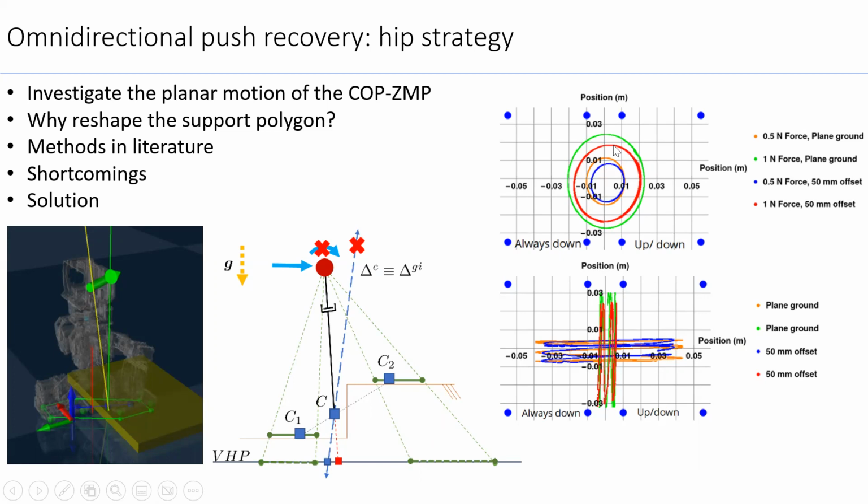We'll talk about why their magnitudes have changed later, but we can clearly see that they have moved towards this foot, which is on higher ground. Now, this means that the stability margin in this case is less. But we know that it is difficult to tip the robot on the side of higher ground than on the lower ground. So this calls for modification of the support polygon.